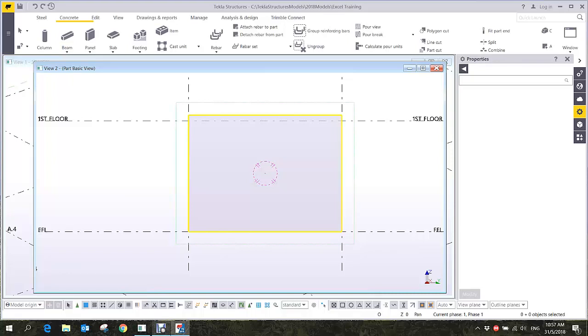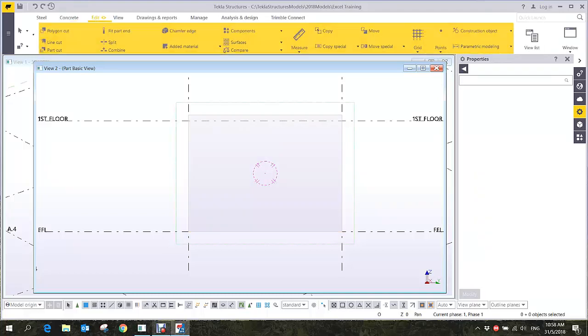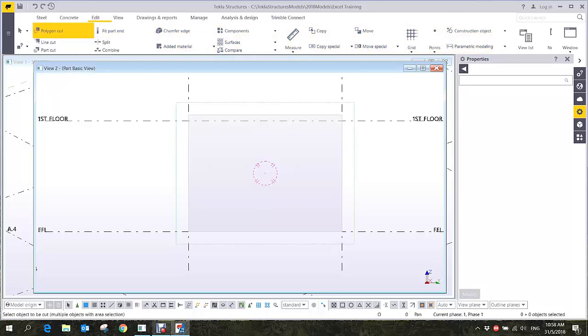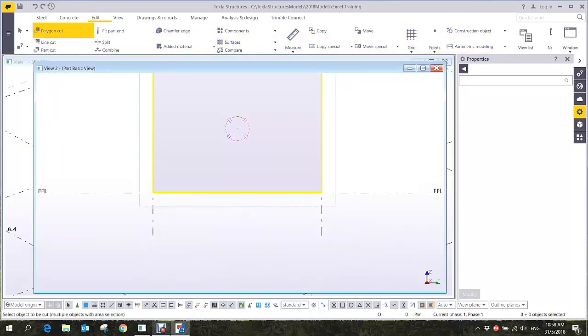So opening, as you can see, you can use the points, right? So without using the points, as I've told you, you can do that way, okay? But there's another way, without moving it, and then I can directly cut on the exact position. So how? This one, edit, polygon, okay? So from here, I know that one is from 800, 16, and then 1000, okay?